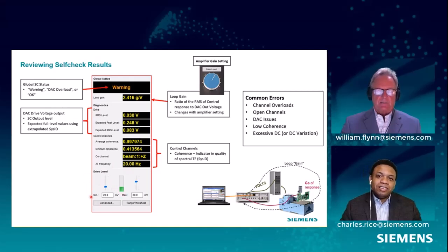So, out of the box, the test lab software is always going to be very, very conservative. I think the minimum default value is 5 millivolts. Well, in a lot of cases that's just in or just above the background noise. And I think the maximum is 20 millivolts. So those are pretty low levels, pretty conservative. This is the default that I use, a 20 millivolt minimum, 60 millivolt maximum. And then you're going to have a number of steps, let's say 5 steps to step up to full level.